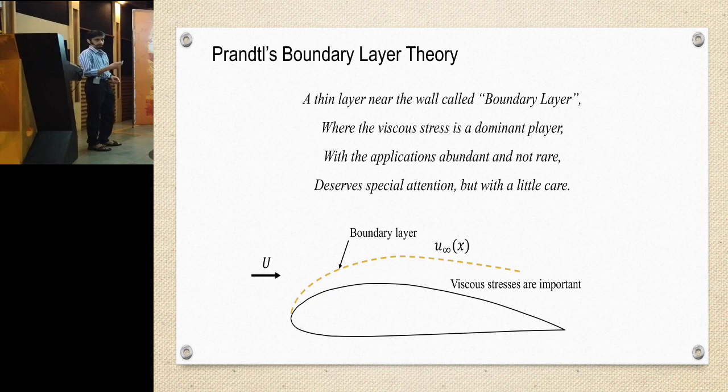especially when you are dealing with the mathematics of this theory. Okay, so it's a highly exaggerated depiction of a boundary layer on this surface. Capital U is the oncoming velocity. Now remember that if you go far away from the body, in the outer inviscid flow, the velocity can change with x because of the shape of the body.